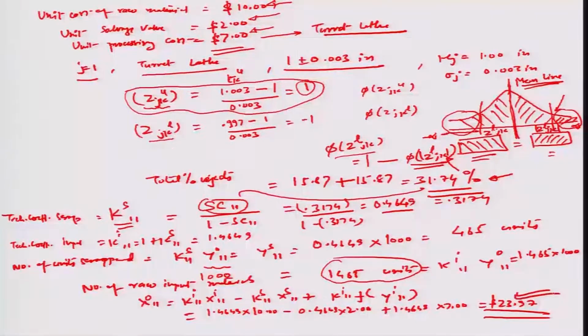So, this is the unit output price which comes out because the manufacturing does not have any option but to use the turret lathe with a certain process capability. So, had the manufacturing gotten a flexibility to extend the design to slightly better or lesser specification limits, and then the quality would not have minded that, or the finance would not have minded that. So, the decision could have been at the very initial phases, just as a concurrent approach normally goes. In this particular case also you could do a reasonable amount of cost saving and improvement of quality. So, that is the defect behind the serial engineering process of having to work on a design given, or forced to work on a design given without having a say in the design itself.